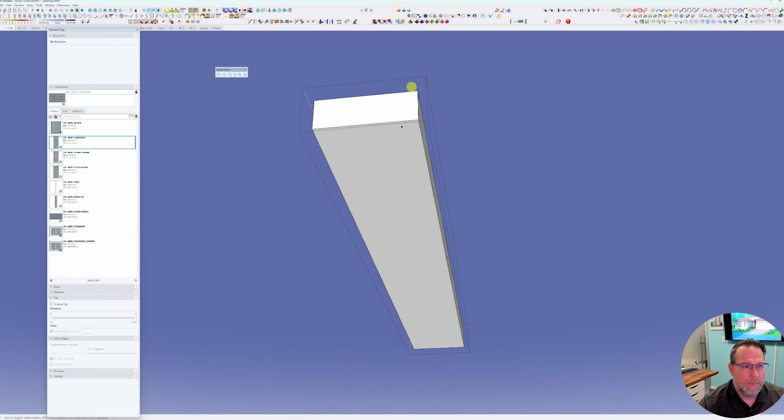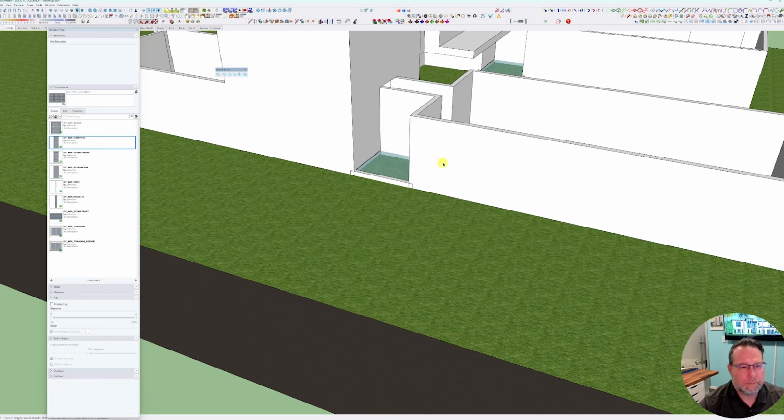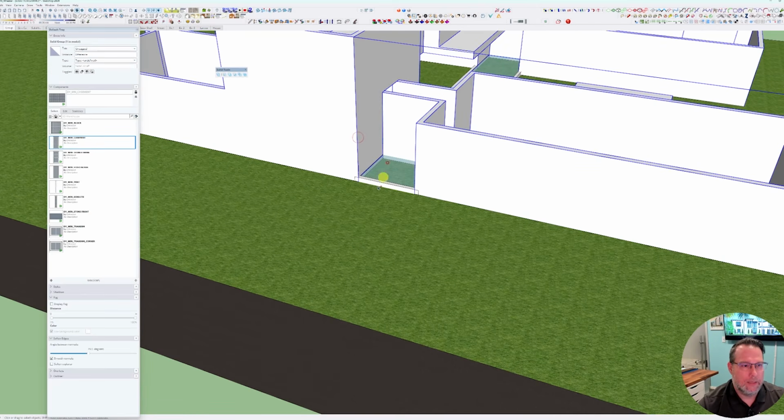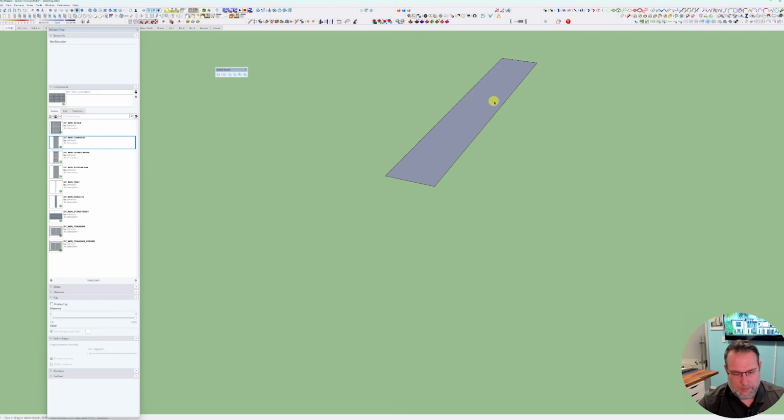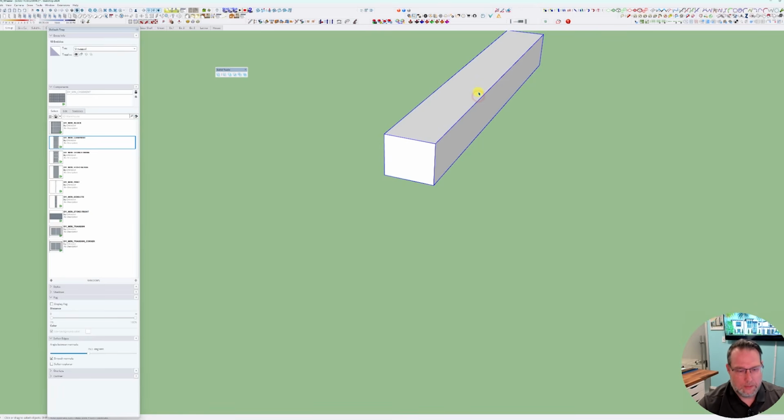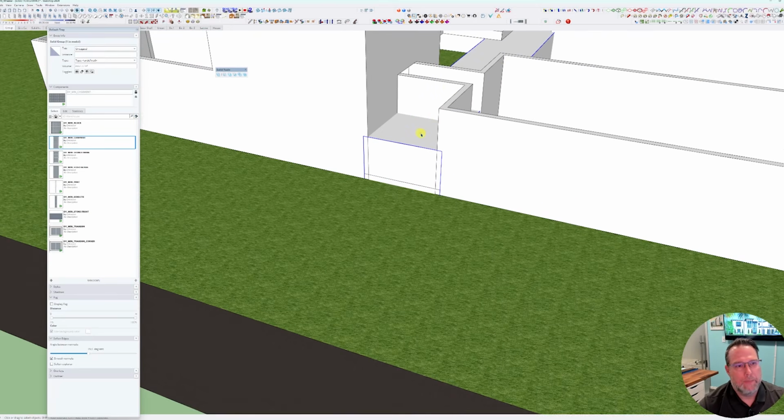And as I was mentioning before, I'm going to select this bottom face. I'm going to copy it. I'm going to Control Shift V. That pasted it into place. I can't see it because it's kind of down below everything, so I'm going to hide everything, hide this, and this is where it came in. And we're going to push pull this, and again, it doesn't matter. I'm going to go 10 feet just to make it big, turn this into a group, and then unhide everything.